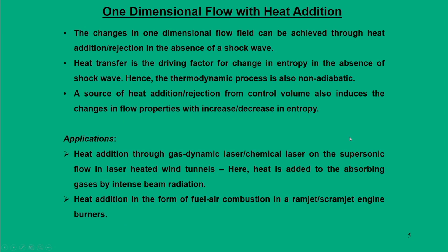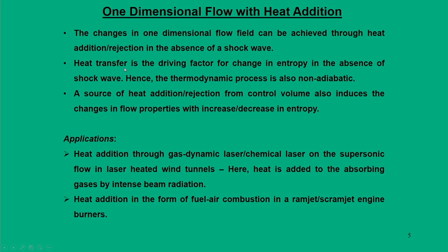Now, just to say what the mechanism of the heat addition process in a one dimensional flow is, in this particular duct we are looking at the flow phenomena through a heat addition process. Of course, there is no normal shock sitting in the flow, where we could have said that there are drastic changes in properties. But what changes the flow properties is the heat transfer.